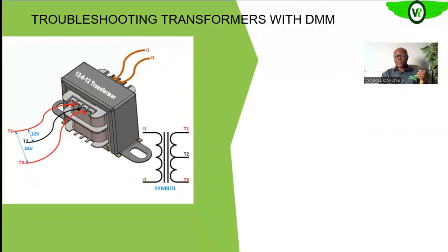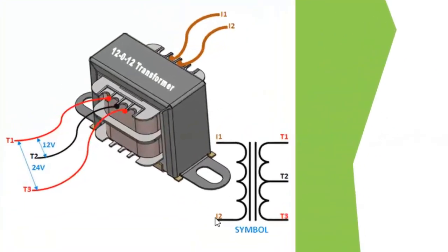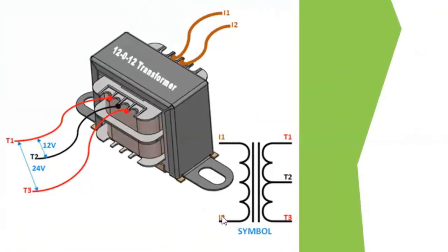So now you can test for continuity of this winding, and that is when the circuit is dead. You can test for continuity of this winding, and you can test if we have a short to the frame or the yoke of the transformer, that is, a short to earth, or to ground in the transformer. Then we can also test turn-to-turn short.